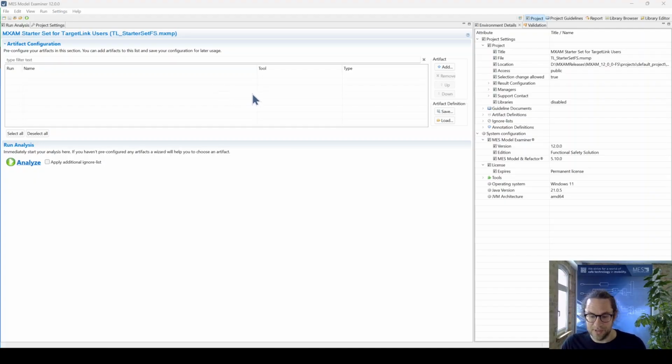And with this major release, we are introducing a new range computation feature, which computes the worst numerical range in order to detect arithmetic overflows, dead code, and design errors on the model level. So by that supporting ISO 26262 recommendation design principles of strong data typing and defensive implementation techniques.